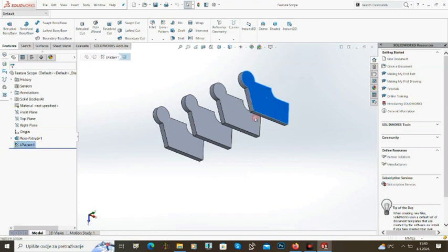You would go here, create a sketch here, create a sketch here and here, right? And then use extrude cut. But that's going to take you a lot of time, and it's going to take more memory. But you can actually create one sketch and you can select which of those solid bodies your cut will affect, okay? So how can you do this? By using the feature scope. So let me show you.